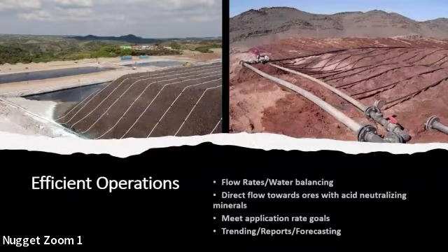Conceptually, the gravel size particles support macropore solution flow, whereas the percent passing the 100 mesh is more the finer particles. That's going to be what's associated with micropore flow, but also that's going to be most relevant to consolidation of the material. The finer textured material will really be the material that undergoes the consolidation.